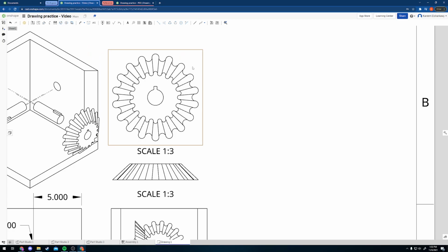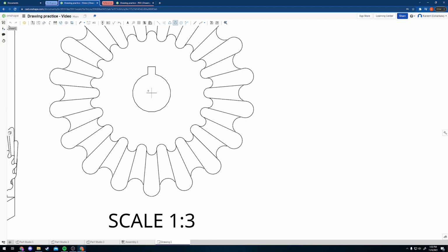And I think to start, I would like to add a center mark to my gear. And doing this is essentially sketching on top of the drawing itself so that I can show relations. So one thing I'm going to do here is I'm going to actually choose next to the center mark the 2-point circle center line. What this is going to essentially do for me is I want to show the diameter of these spokes. But a better way to do it would be to actually just draw a circle from the center. Sometimes you have to play with, you have to mess with it.